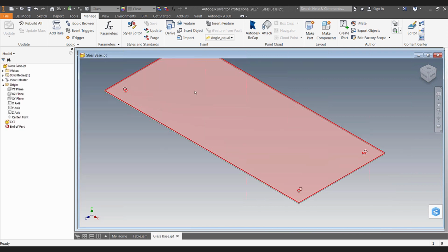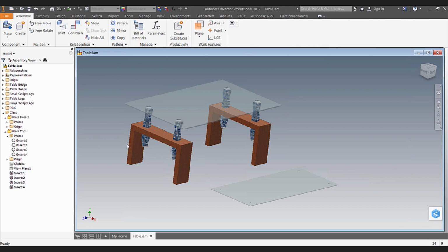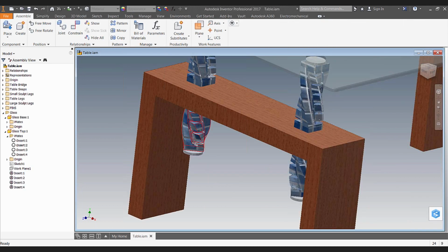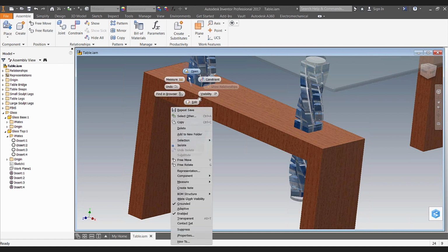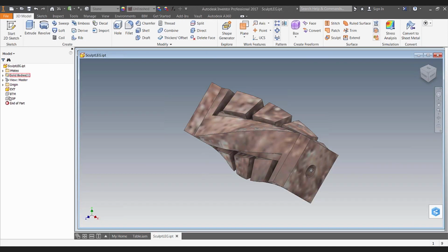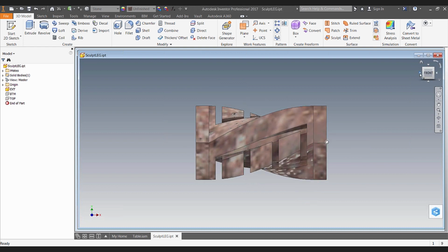Okay, so I've done that. That's one half of the constraint set that's in there. I could drag and drop those things just like I did the other glass, but what I want to do is I want to go into my other side here, and this is going to be applied to the bottom glass. So I'm going to open this up. Oh, and here's where I actually had top and bottom. So, obviously, when you're applying an iMate to something like this that really does have a true top and bottom, if I tell it to match to the top, that's where it's going to go. So I kind of put some planes in here to help me remember which is the top and the bottom.